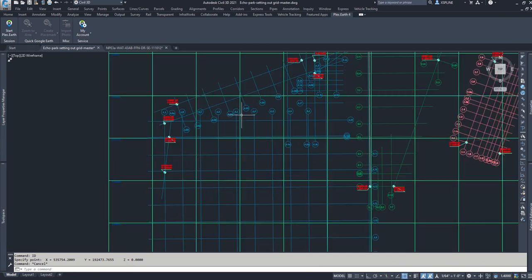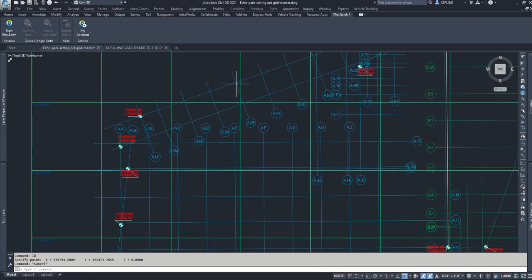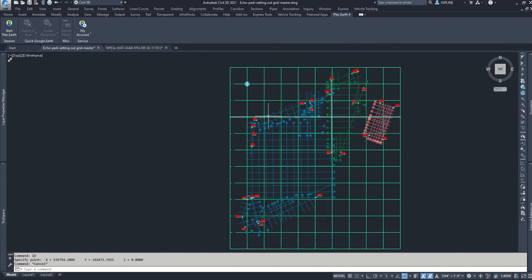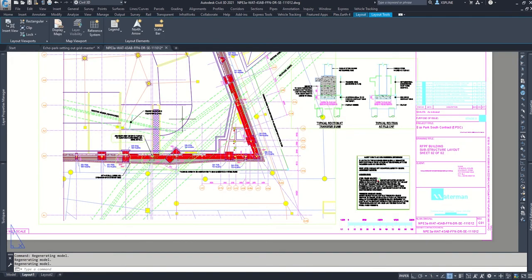So we know that's actually in the correct coordinated space. What we're going to do now is, because there are grid lines here, select two intersections of grid lines, and then pick the same two intersections in this drawing and align the two. So let's look in the model. I'm in paper space now, so go to the model space.